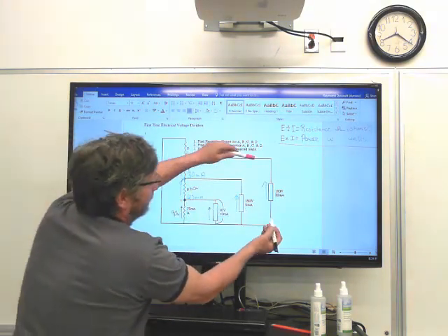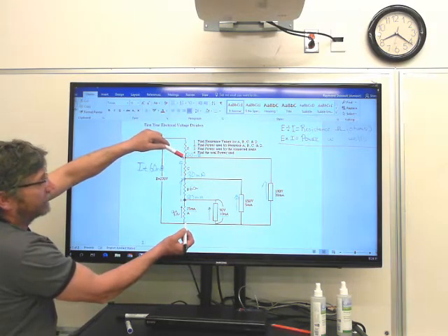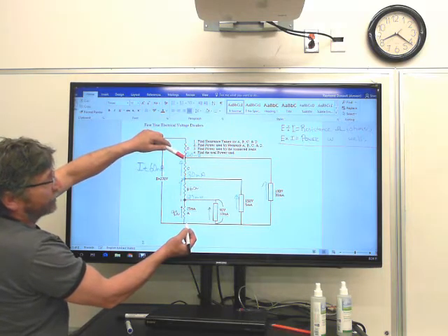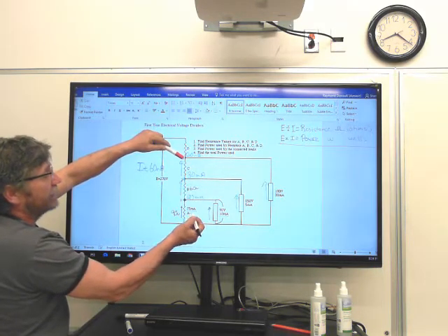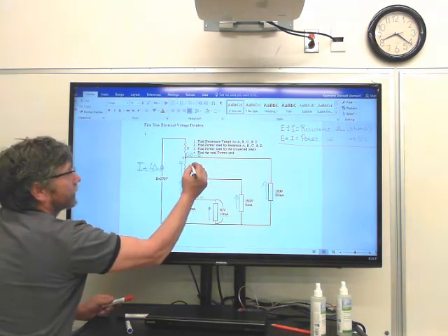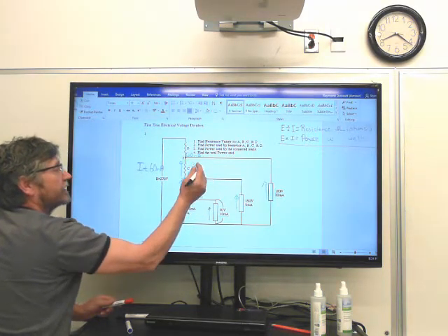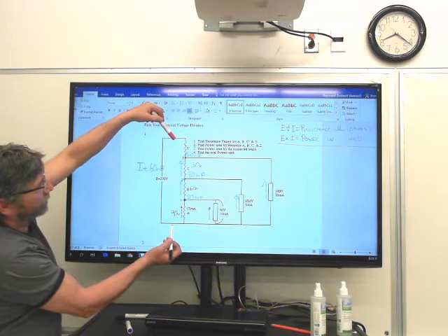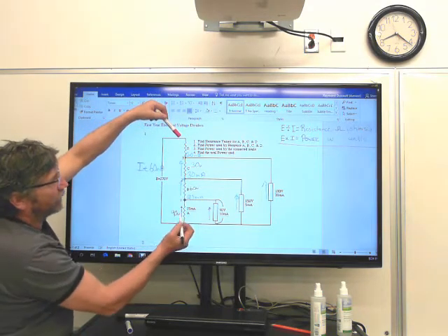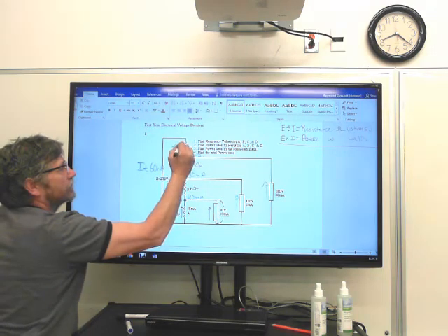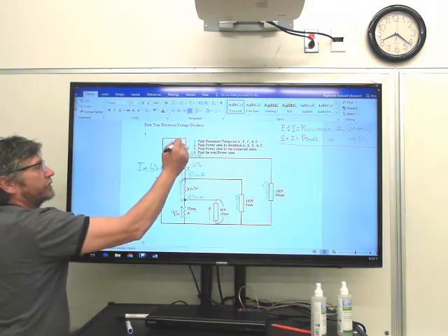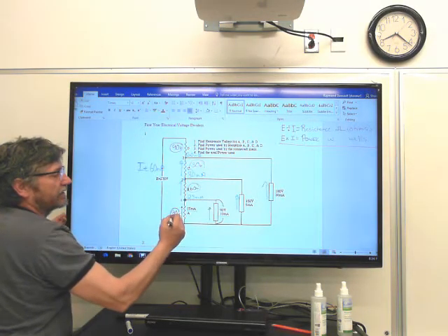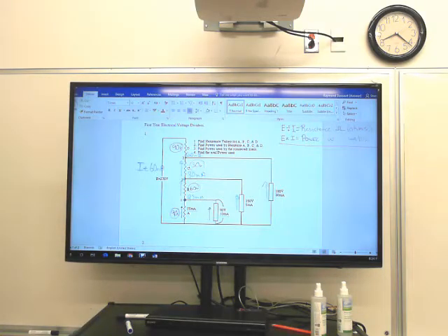Coming right here again with my voltmeter is 180. Slide it all the way back because there's no drop in these wires because it's virtually resistance free. So we've got 180 here, less 90, less 60 equals 30 volts on resistor C. Same thing goes here. 180 here. If we go up here, we go back, that's 270. Less 180 is 90 volts on resistor D. I like to circle my voltage drops to indicate that they're voltage drops. Okay? So there's my voltage drops on my divider.